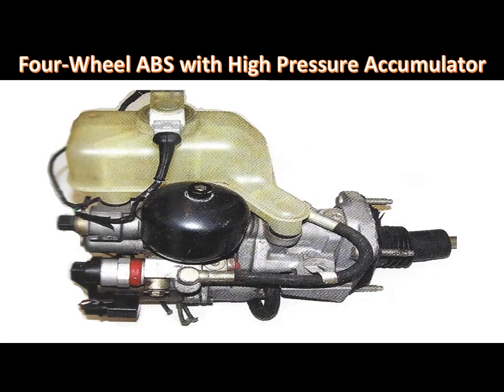The pump maintains a brake fluid pressure of 2,000 to 2,600 psi, or 14,000 to 16,000 kilopascals, in the accumulator. If the accumulator pressure drops below 2,000 psi or 14,000 kilopascals, a pressure switch on the master cylinder signals the control module to start the pump motor and increase the pressure.